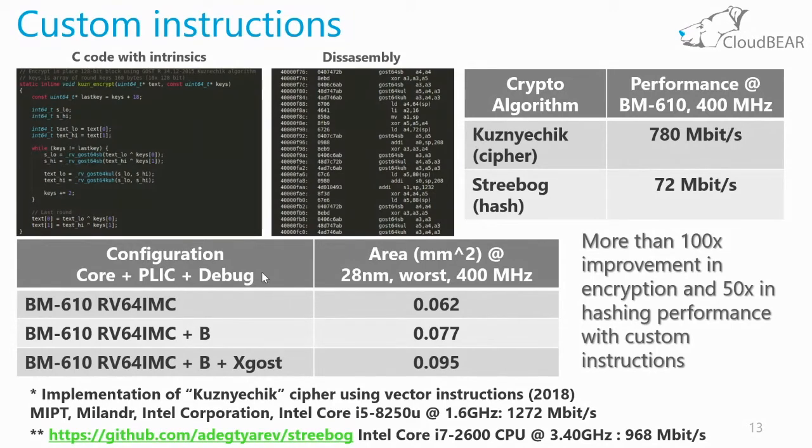So we added about 10 instructions which focus on the cipher algorithms and hash algorithms. And we also use the power of the B extension to speed up some operations. Note that we implement all this across all toolchains, so it's integrated into the assembler and GCC, and we're providing the intrinsic functions and some library to the customer, which allow them to run these algorithms on the CPU.